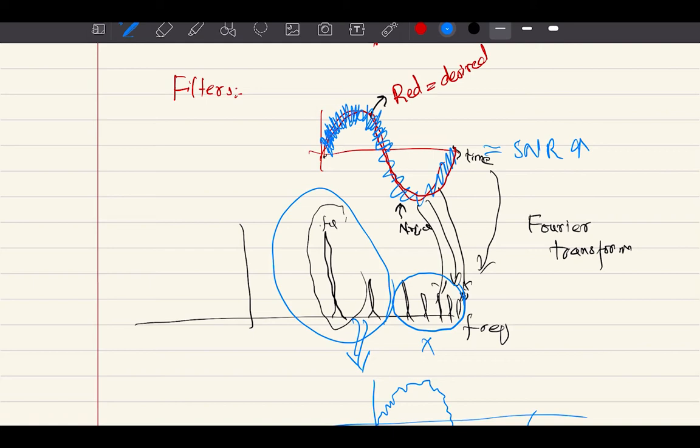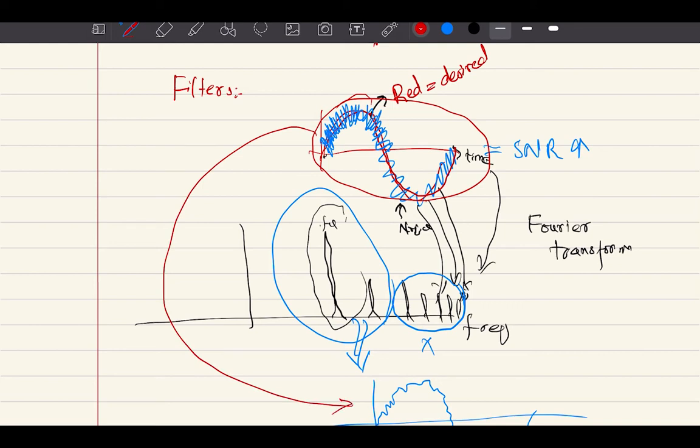So you can see that before it was very noisy, and after processing it through a filter, your signal has become very clean, although there will still be some noise there, because I told you that we keep the frequencies closer to the fundamental frequency, which means that you still have some noise there.